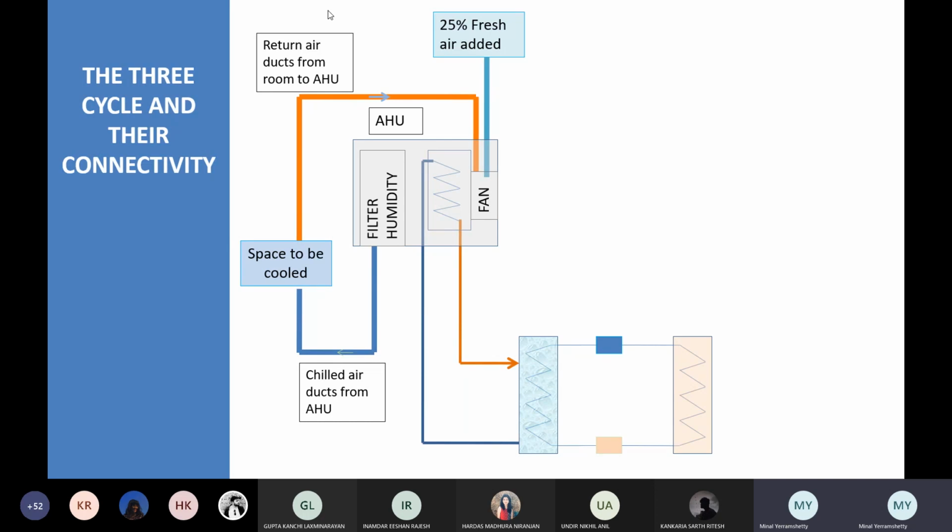So suppose the requirement of my AC has stopped, the office is closed, it's 6 in the evening, people locked up and went out, and they forgot to switch off the AHU, but somebody comes and switches off the AHU. The moment somebody switches off the AHU and this stops, the condenser automatically stops. Okay, that's how things are planned.